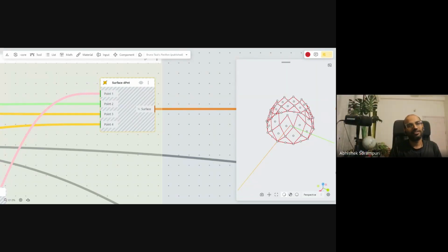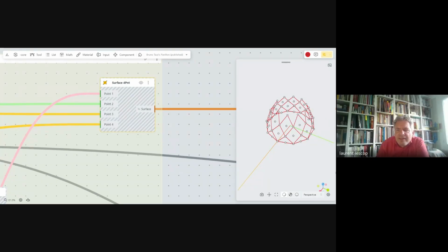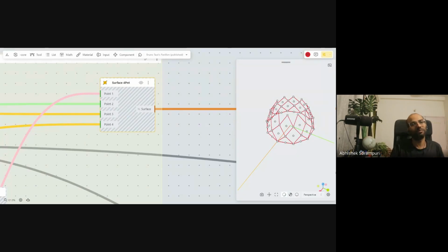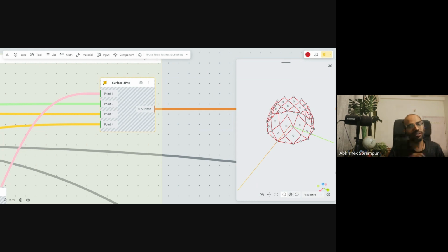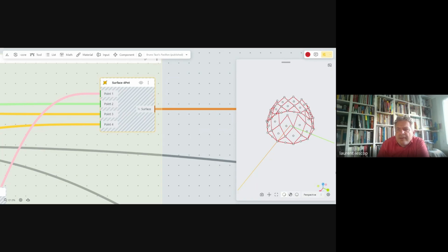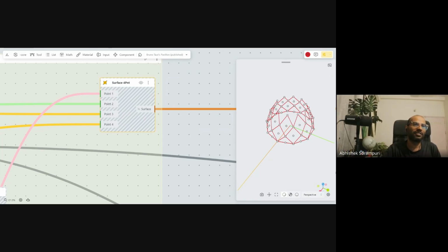So there I realized that we would have to evaluate each and every curve to see whether it has to be a triangle or has to be flat for the glass to come. There we used a surface 4 point and it was generating these doubly curved surfaces, like a bent surface. But we had to evaluate and check every panel, whether it is flat or not. If it is not flat, then we had to level up all the panels. Wow, interesting.